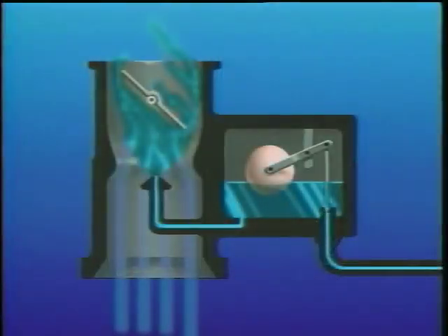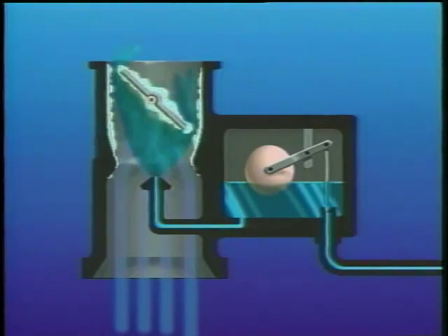Float-type carburetors are highly susceptible to icing due to where vaporization occurs. As intake air passes through the venturi, it cools. Further cooling occurs during the vaporization process. This drop in temperature can cause moisture to freeze and adhere to the internal parts of the carburetor.